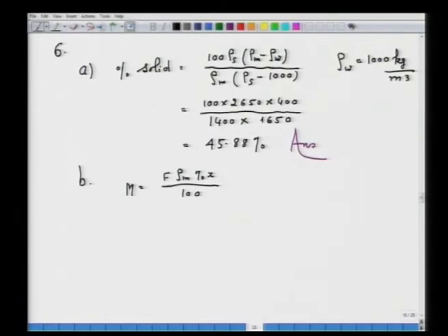So, all that I have to substitute the value and I have to get the answer. F is the flow rate, that is 1 upon 8, 1 liter, it takes around 8 seconds. So, if I convert in the units, then it will come around 3600 upon 8000, that will be in meter cube per hour.